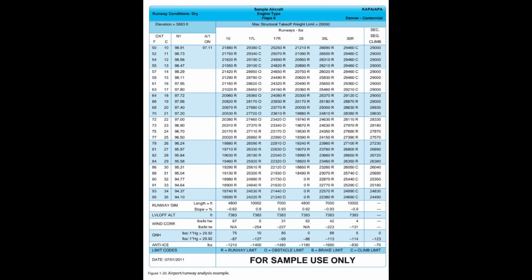The computations also consider flap settings, various aircraft characteristics, runway conditions, obstacle clearance, and weather conditions. Obstacle data also is available from these service providers for operators who desire to perform their own analysis using the OEI climb performance and flight path data furnished in the airplane flight manual or when using an aircraft electronic performance program supplied by the manufacturer or other service provider.